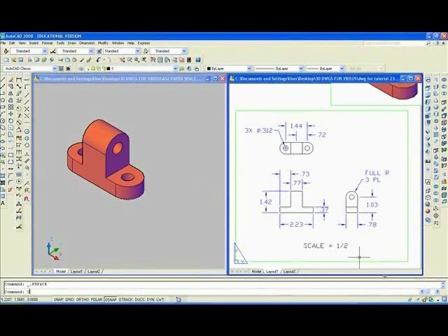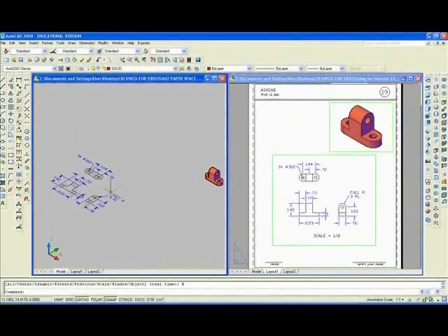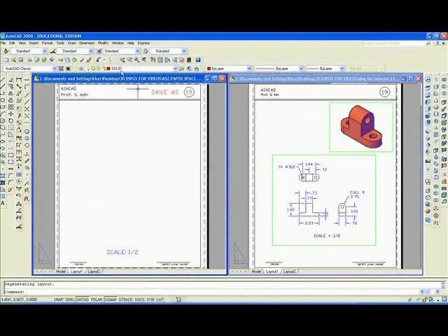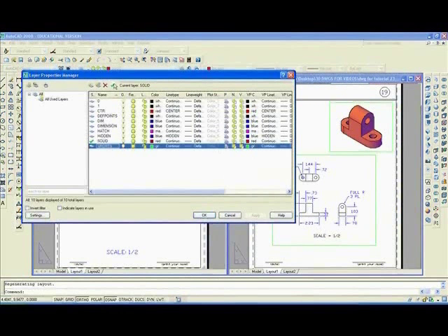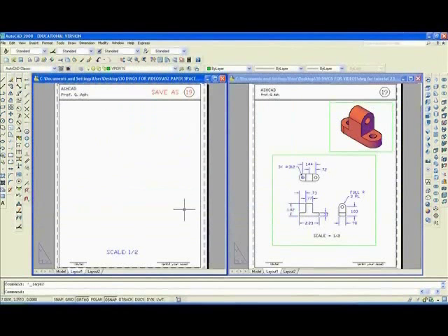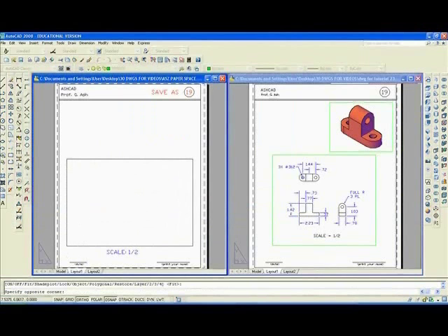So now I'm going to type Z, enter, E, enter. Click here and type Z, enter, E, enter. When you weren't looking, I put the dimensions on the object. And so we'll go into layout mode, and we're going to change the layer from viewports, make it current at viewports. Okay, and I'll type MV. Hope this will come out right. I'll leave a snap on. So it looks like that.